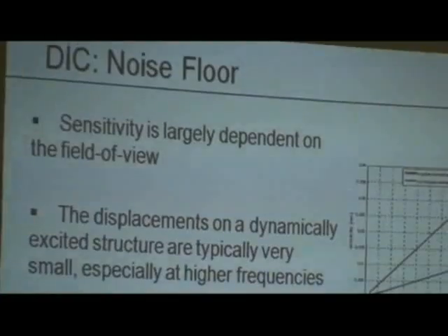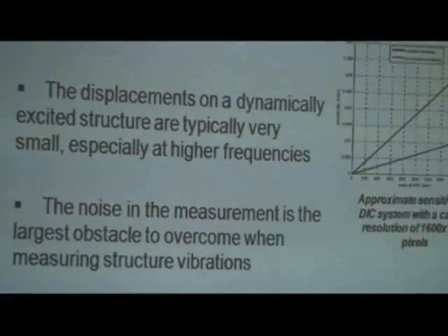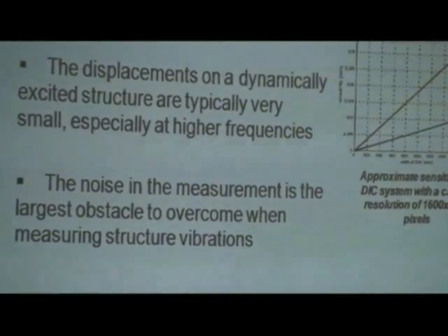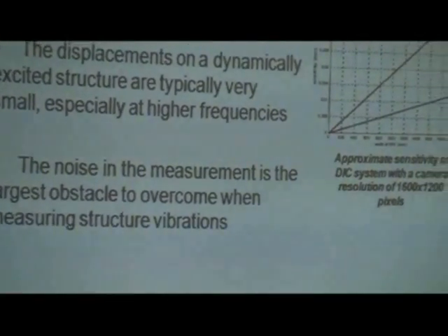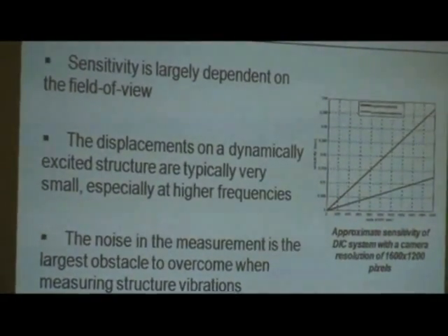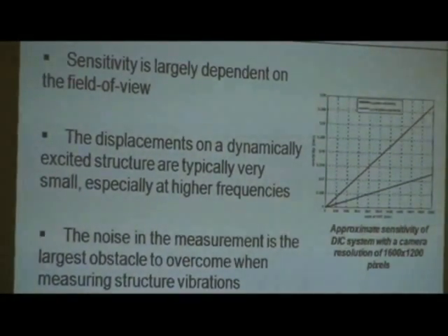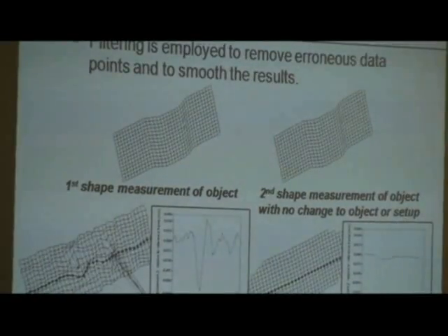The thing about measuring vibration is that you're typically using accelerometers, and accelerometers measure well when the frequencies are higher, because there's an omega squared term with the acceleration. This technique measures displacement. So if you're measuring acceleration and you want displacement, you have to divide by omega squared, and so it becomes more sensitive at low frequencies. The critical thing is displacement, and for vibration, there can be very low measurements. So we have to be mindful of whether there is enough displacement for the vibration you're interested in.